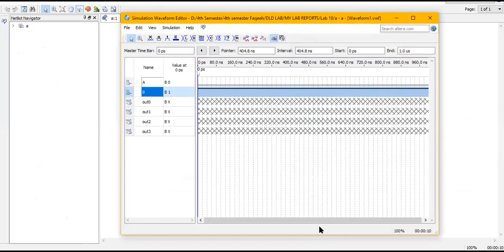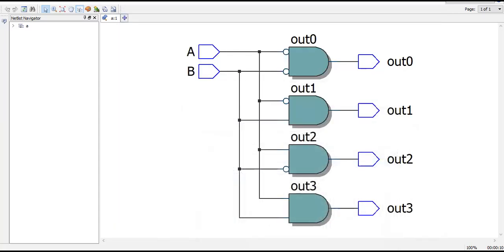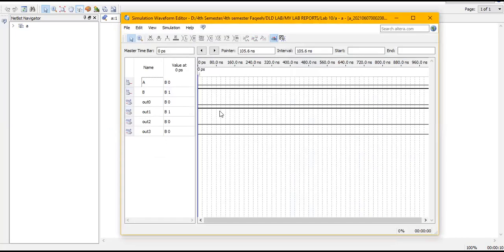If I see the waveform, I'm giving it 0 and 1. It is the input which we got as the output from the encoder we did previously. So 0 1, and the output should come as 0 1 0 0, which was the input in the previous case. Here I have simulated it, and it's 0 1 0 0. As you can see, it's working nicely and perfectly.